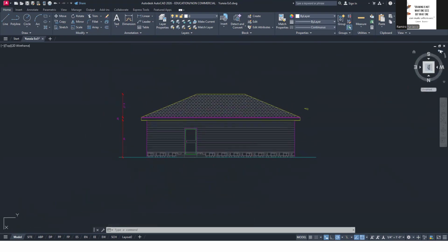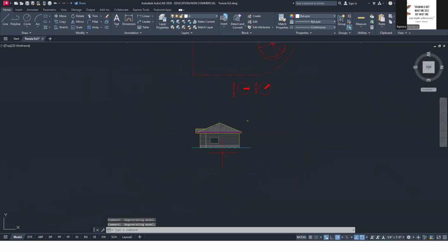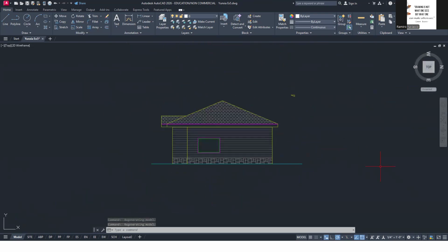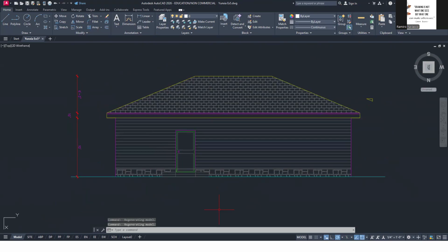Did you take a photo of the east elevation? Sorry. So east elevation. Okay. And then UCS. And then go north. That's the north elevation. Again, take a photo. And then again, you can say UCSV, right? Quick. For me, it's a lot faster than doing UCS restore name.